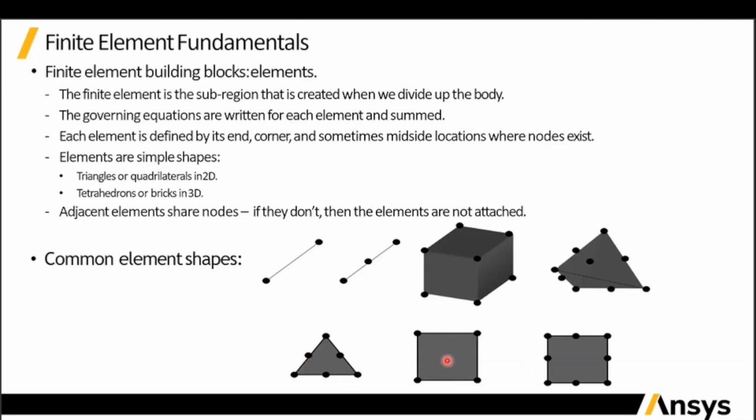So this is how it works. That time, plane stress condition, plane strain condition, or axisymmetric, that is, symmetric about one particular axis, you can simplify your problem and consider it as a two-dimensional problem. And for the rest of the problems, whatever model you are working on, let us take the example of a pump housing, or just consider your mobile phone. You can simulate your mobile phone as well. This is a three-dimensional case, so at such times you will be using 3D elements.